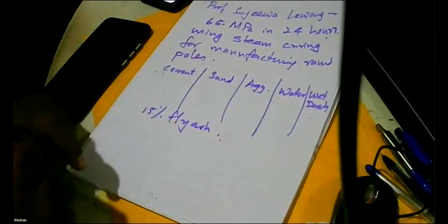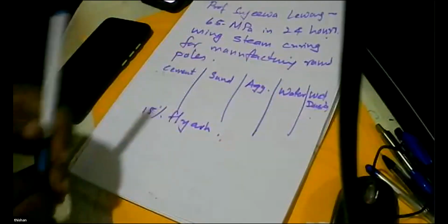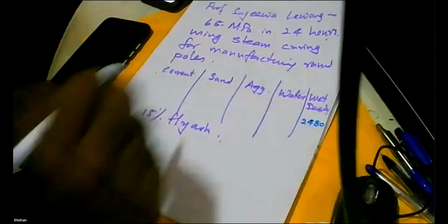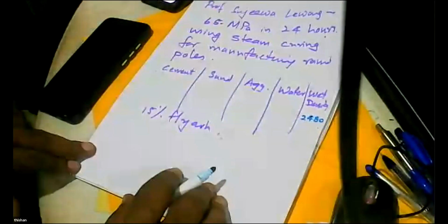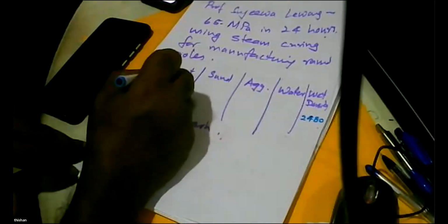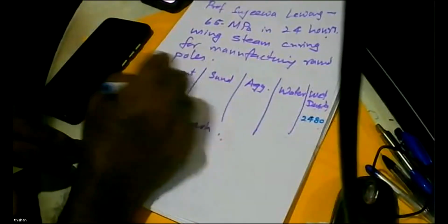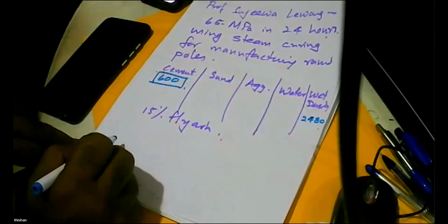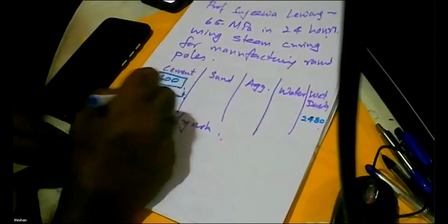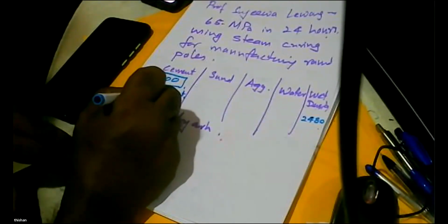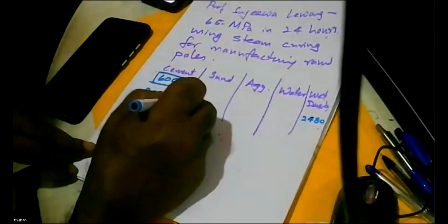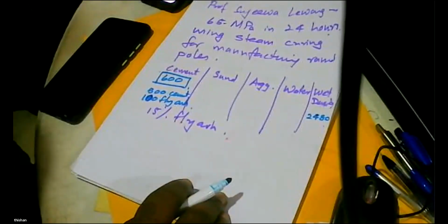So I started plugging in numbers. So this is the time that it took. Okay, I said, 2180, because I'm going to use some fly ash, because fly ash has a lesser density than cement particles. And so I'd like something like 600 cementitious material. So I said, okay, 500 cement, 90 or 100 fly ash, just about that. Because when it says 15%, you need not be exactly 15%.